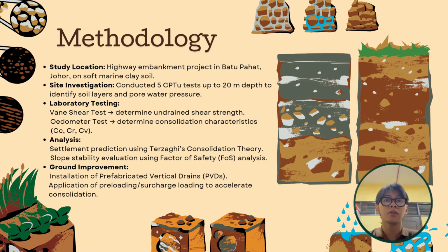Next is site investigation. Five CPTU tests were carried out to a depth of 20 meters to evaluate subsurface conditions, and the tests provide data on soil layers, cone resistance, and pore water pressure, helping to identify weak soil zones.